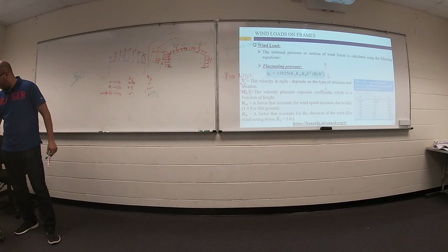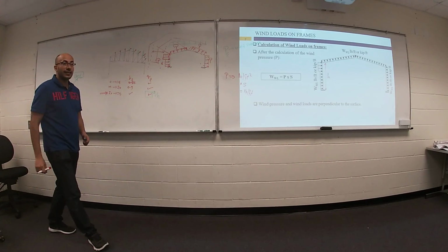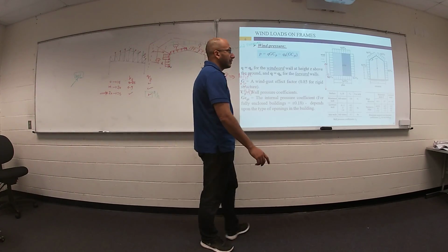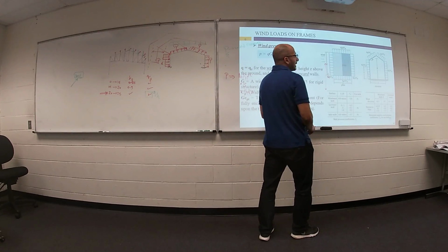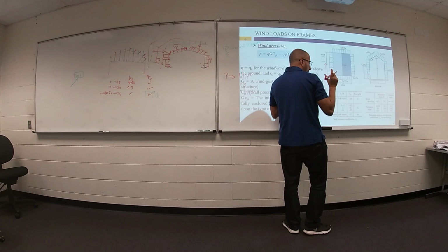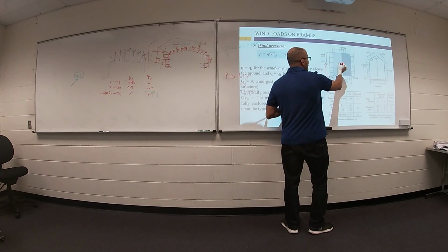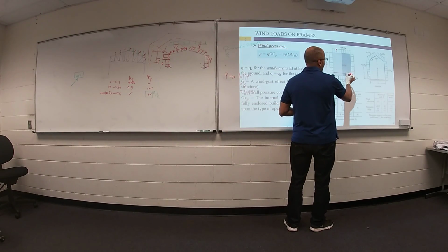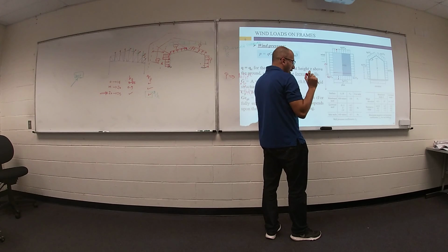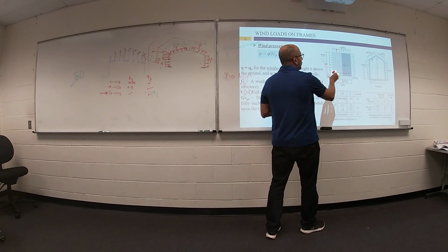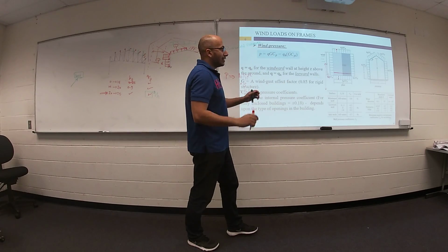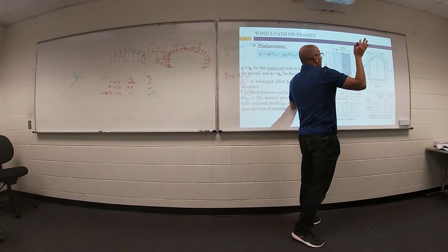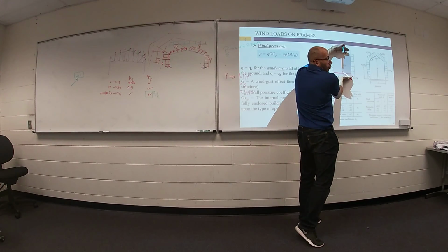Can I ask you a question on slide 6? Yeah. Why don't we worry about the plan view there? Why don't we worry about those other, this one and this one? Yes. We don't care. Because our concern is your main system. These forces will not be supported by your main system. Your main system is in this direction. That's right. So our main concern is the main system. This pressure will be supported by end gables, side girts at this location and this location.